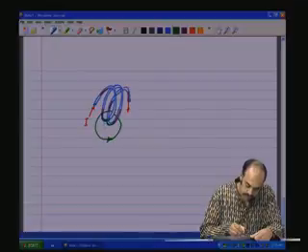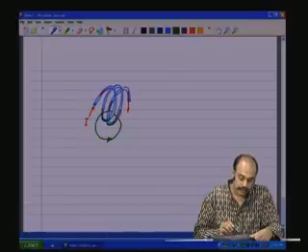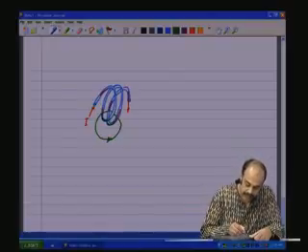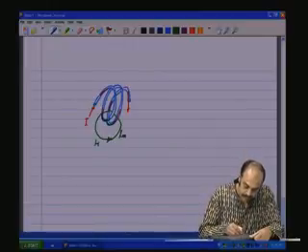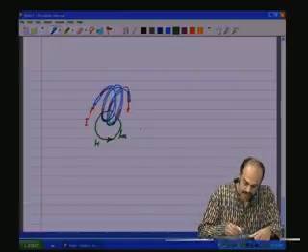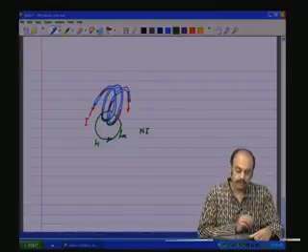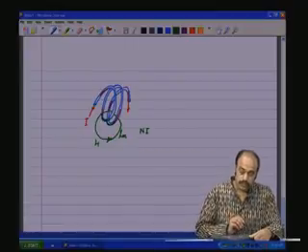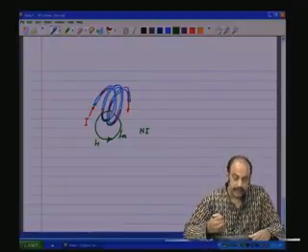So if there are two, or if there are n such conductors, each carrying current I in this coil, and that is causing a field of intensity H being created, then integrating this H around this magnetic path length Lm will give you Ni, depending upon how many turns you have put. So this is the principle in which Ni, the magnetomotive force, is created.